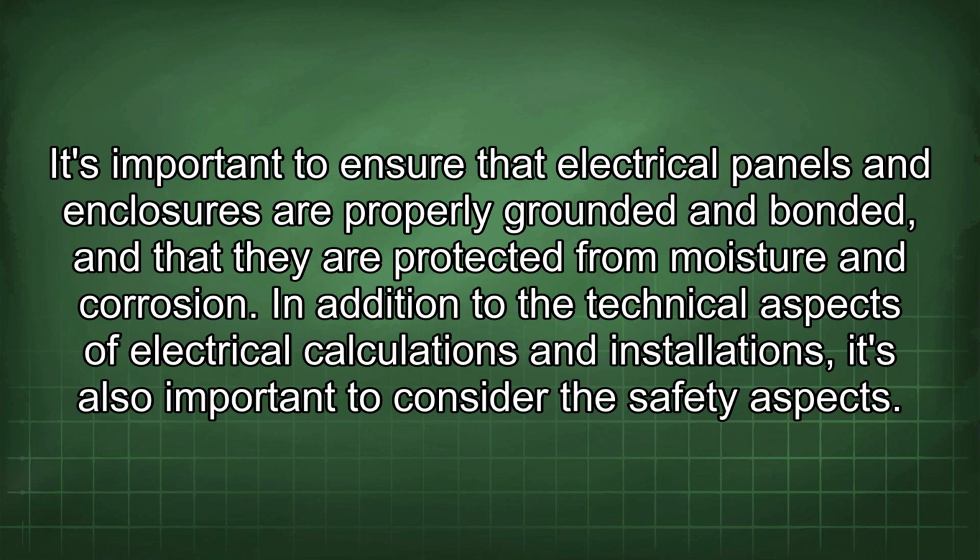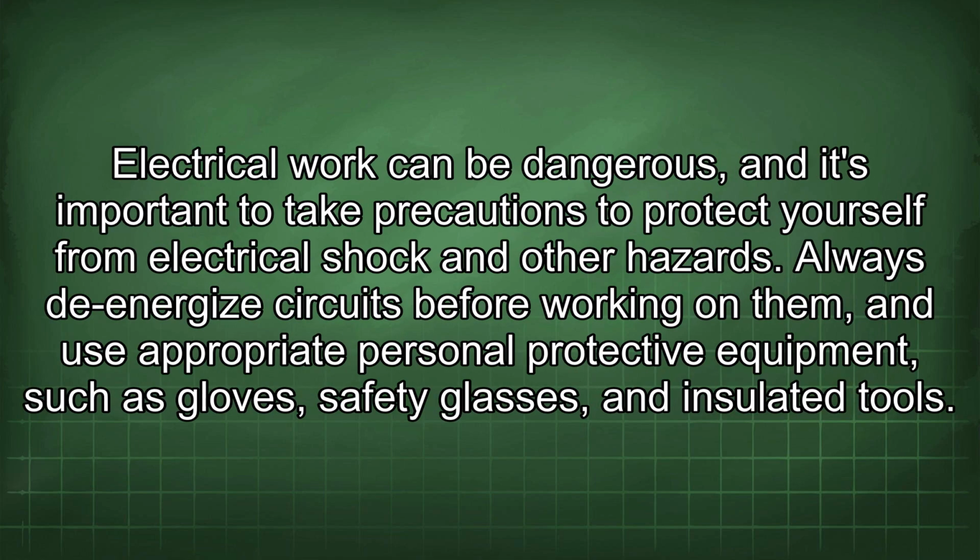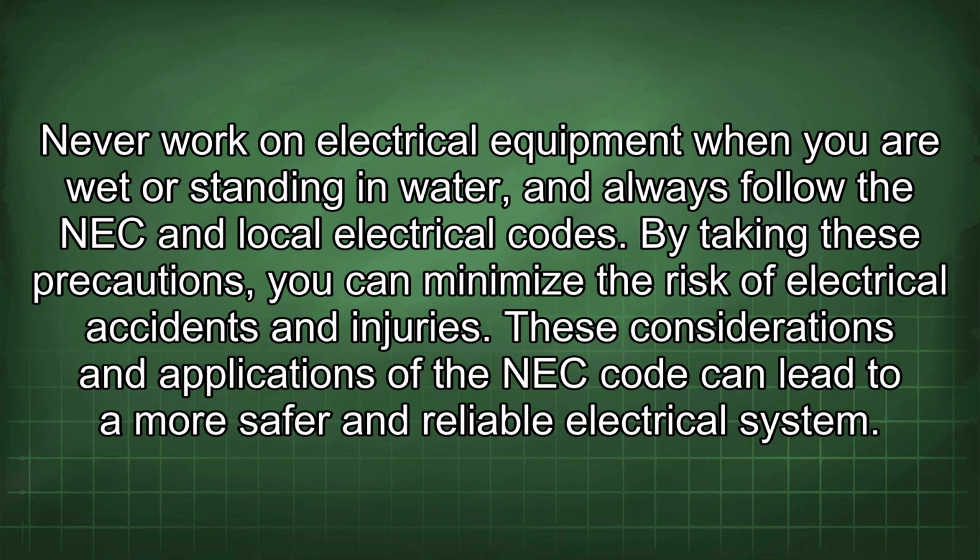In addition to the technical aspects of electrical calculations and installations, it's also important to consider the safety aspects. Electrical work can be dangerous, and it's important to take precautions to protect yourself from electrical shock and other hazards. Always de-energize circuits before working on them, and use appropriate personal protective equipment such as gloves, safety glasses, and insulated tools. Never work on electrical equipment when you are wet or standing in water, and always follow the NEC and local electrical codes. By taking these precautions, you can minimize the risk of electrical accidents and injuries.